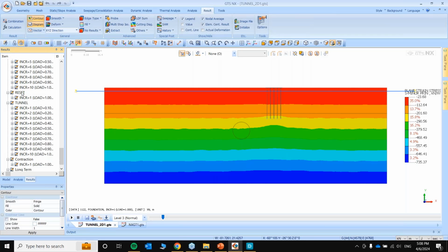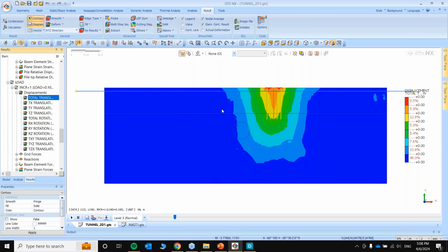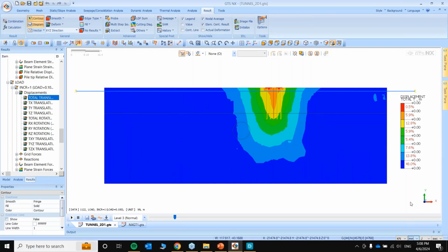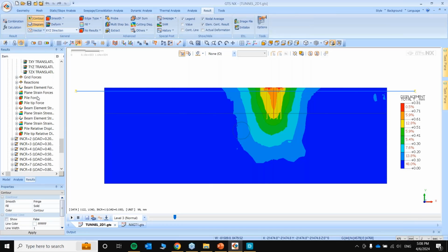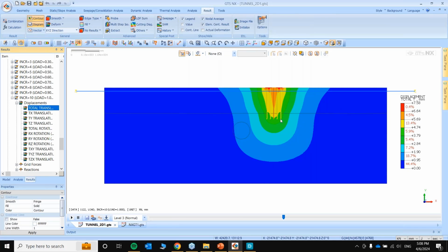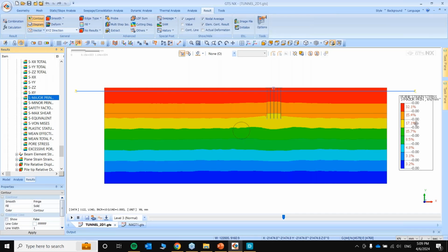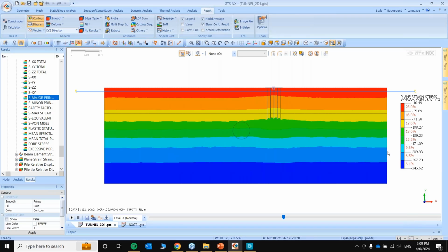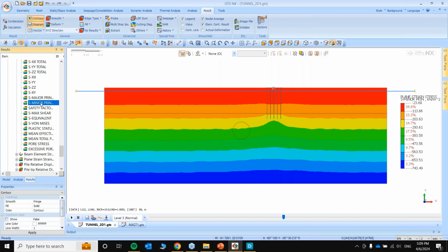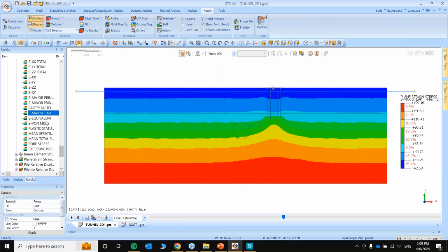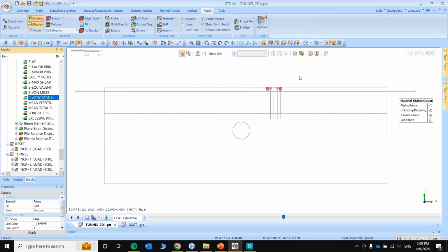Now in this part, that is the loading stage, you will see the change in the ground stress scenario. So we have applied the load in 10 increments. Okay, I'll change it to millimeters for the first increment. Then when the load is fully active, the deformation is now 8. Then the ground stress redistribution, major principle, minor principle, then the shear zone. We check for any plastic areas. So we have a little bit of plasticity around here on the edges.